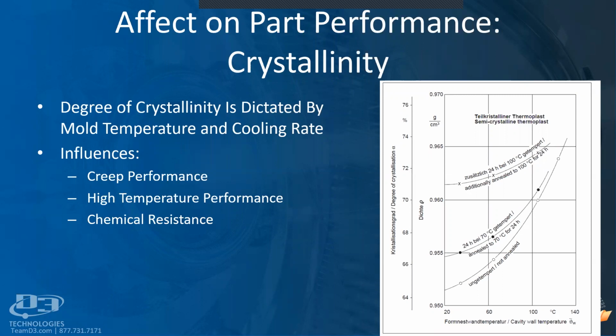It's not something I can do in line, and it's not something I can necessarily measure and quantify easily across a lot. But really the reason we're talking about crystallinity is that it's going to really influence our long-term performance or our creep performance of our plastic part, and again, our high temperature performance of our part. Maybe not so much of a difference at room temperature, but our high temperature performance. So if we're looking to use this in elevated above room temperature applications, then that's going to influence us.